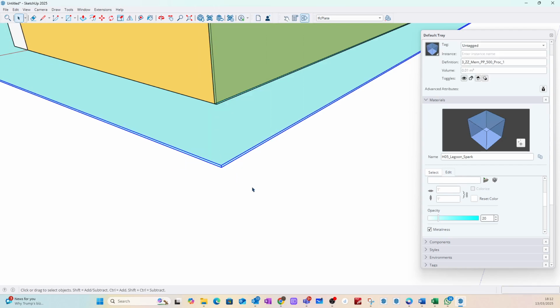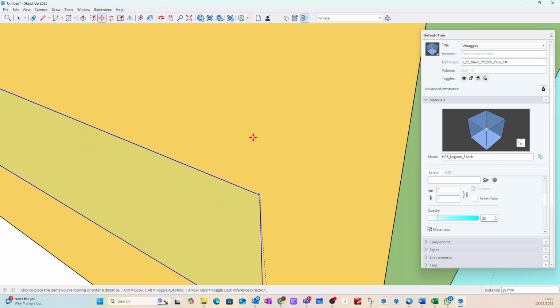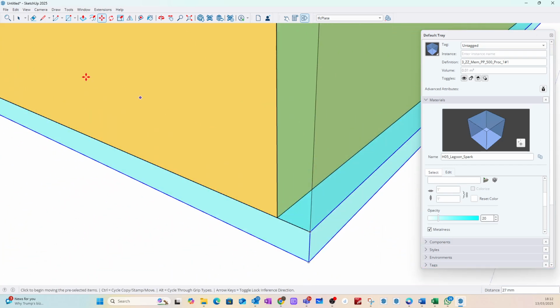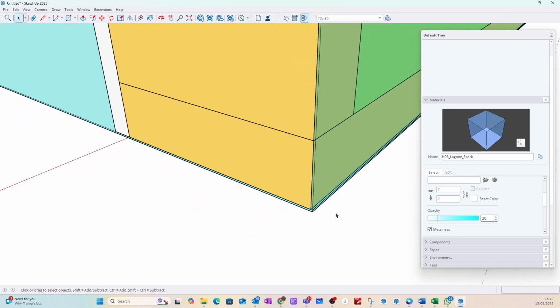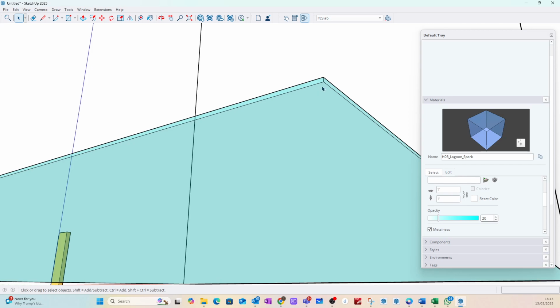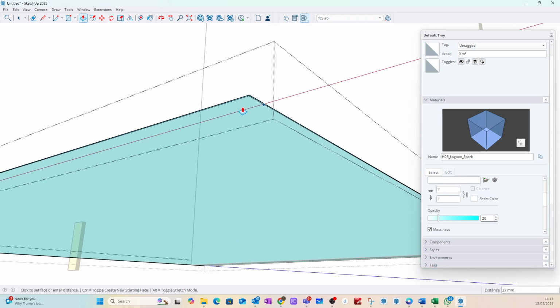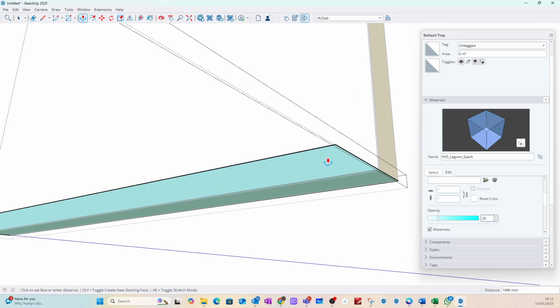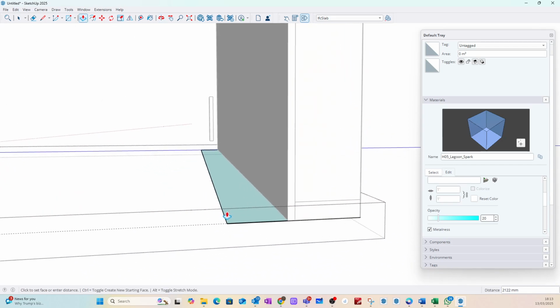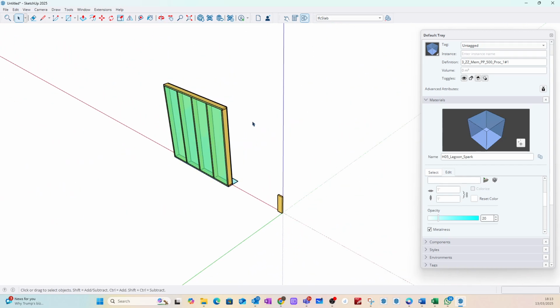Let's make this unique, and we'll place it. This is just because the sheet is actually just the roll sheet. You want to have it placed underneath the wall and come back into the room a little bit, maybe not as far as that. And you would then somehow mastic or some sort of way of sealing it to the underfloor. In this particular case, you could literally mastic that straight onto the concrete under there. There's a floor going to go on top of that. But for just now, that is our one wall complete.